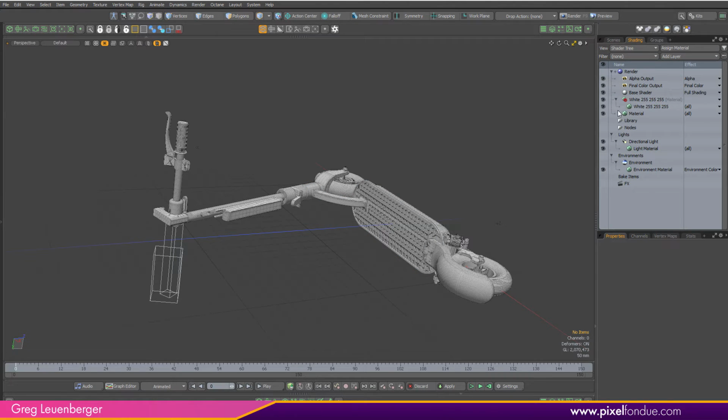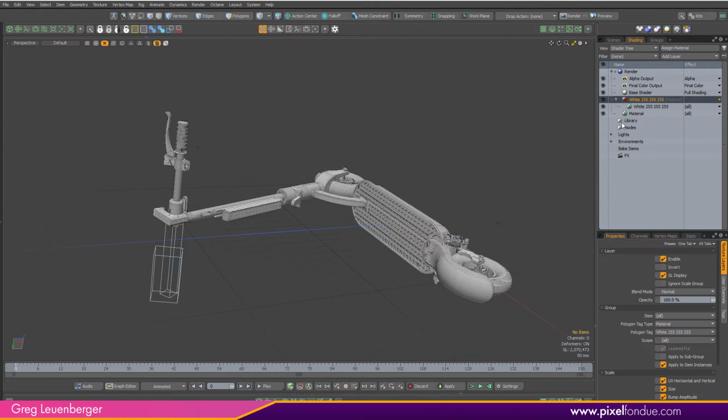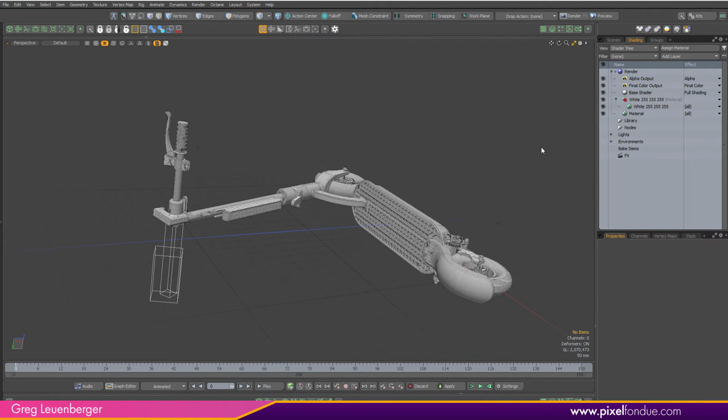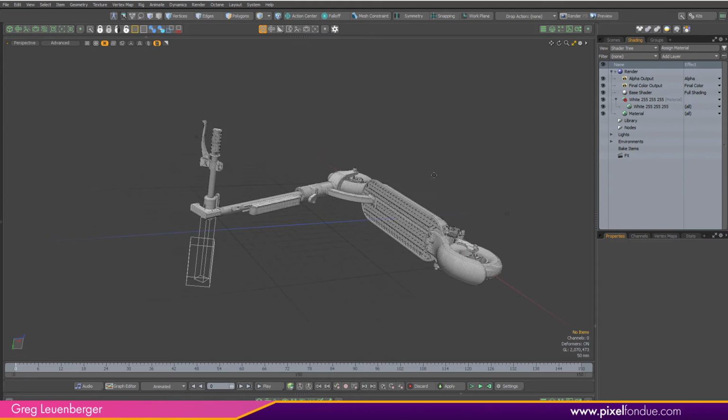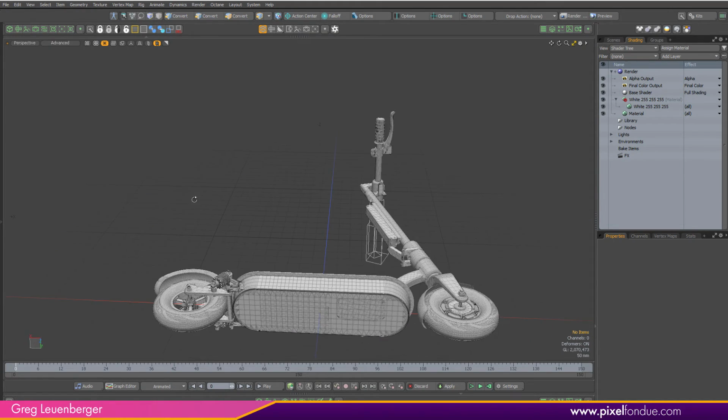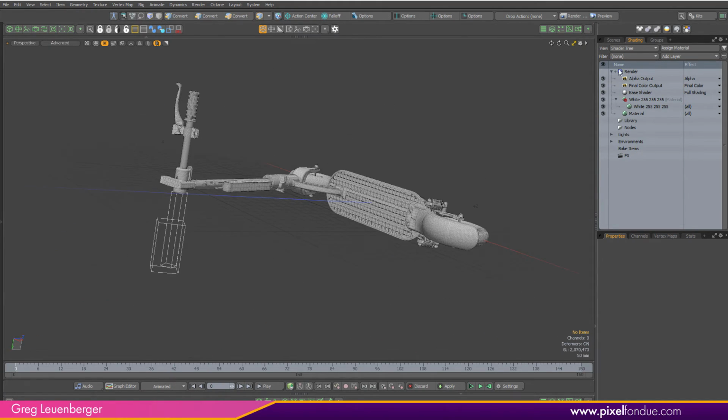If you look at the shader tree, it didn't bring in anything. Just white material, right? So this didn't bring in any materials, and often you just don't get those with STEP files and Power Translators. So let's first look at our replicators and our geometry. You'll see two folders here. One says replicator particles. It's an empty mesh with a couple of other meshes parented underneath it.